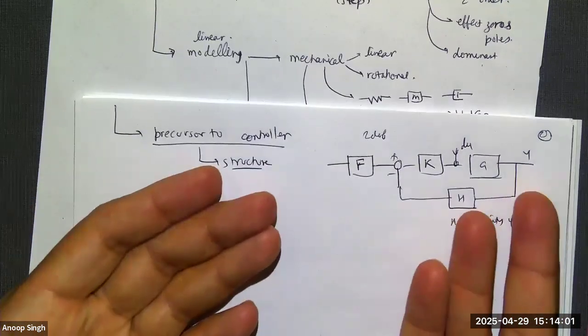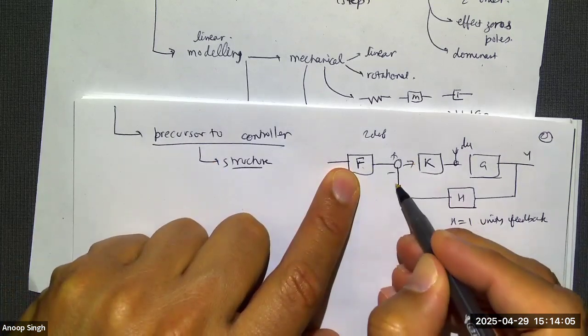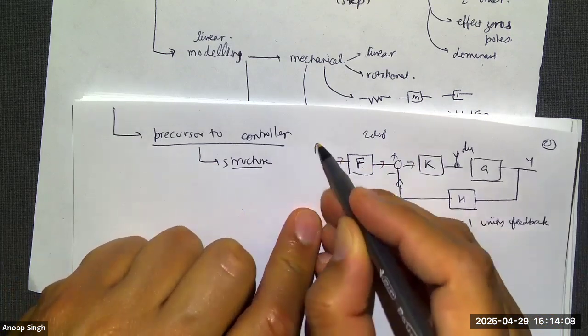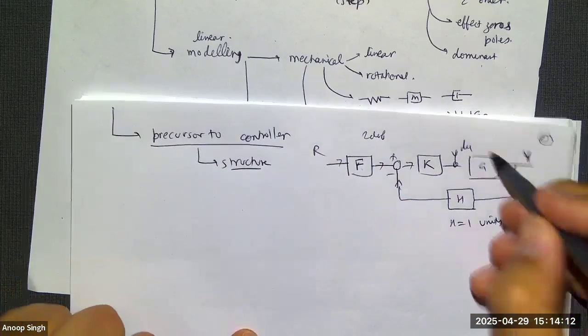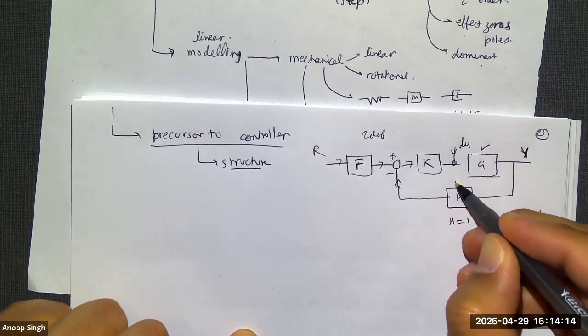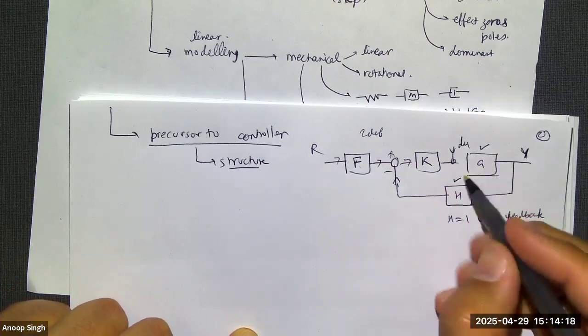And so this is a block diagram. It's a combination of many blocks. Each block is like a differential equation or a transfer function. And the idea was that we are given the value of G, we are given the value of H. We choose a sensor and then that's fixed. The plant is given to us.